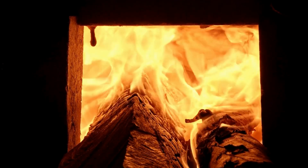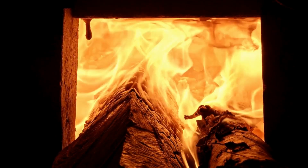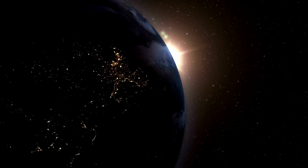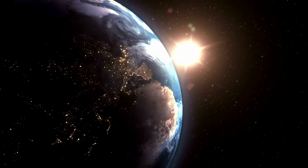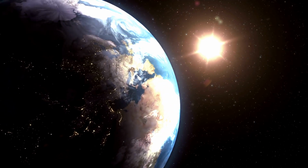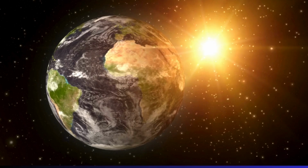Radiation heat transfer occurs when energy is emitted in the form of electromagnetic waves, primarily infrared radiation. Unlike conduction and convection, radiation doesn't need air, water, or any other medium to transfer heat. It can occur even in a vacuum. The sun warming the earth, the glow of molten metal, and the heat radiating from an engine block are all examples of this process in action. That's radiant heat, traveling millions of miles through space.